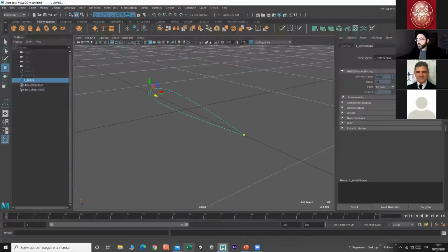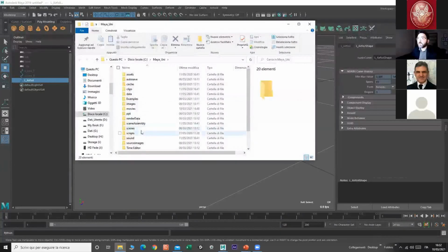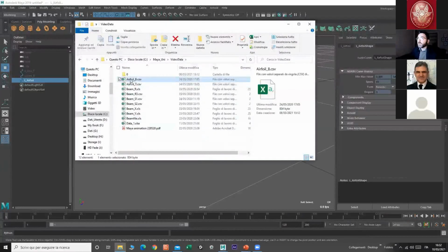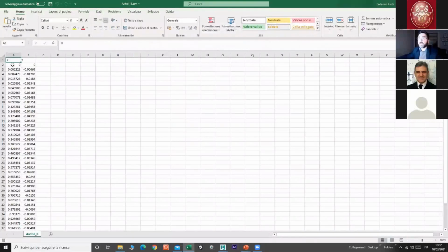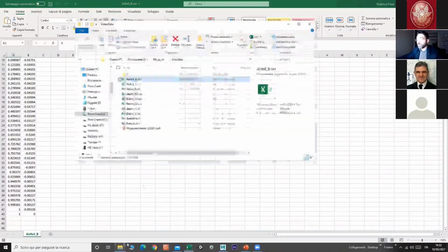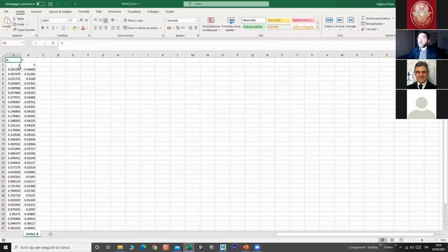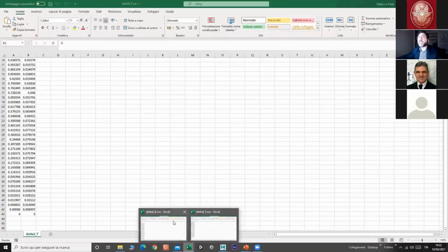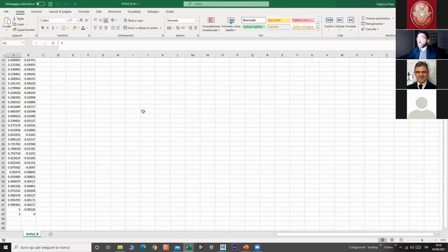Another thing is that if you open your profile, your polar, go on the data, the airfoil bottom, as you need to have the same point for start and end of the top and bottom of the profile. So if you see the top, you have 0, 0, and 1, 0, and on the other, 0, 0, and 1, 0. This is important.